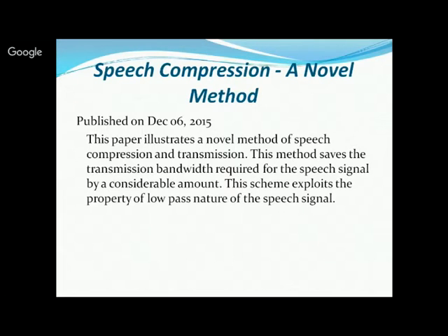The speech or audio signal has the quality that maximum information is in the low frequency signals. So we cut the high frequency signals by passing through a low pass filter, and then we exploit those signals for compression or for extracting information from the speech signal.